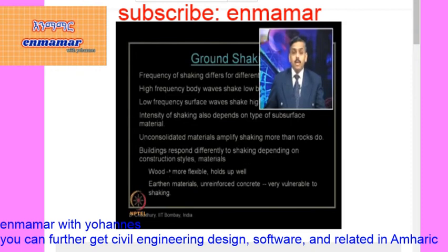That's why in earthquake-prone regions or hilly terrains, mostly wooden constructions are preferred, whereas earthen materials and unreinforced concrete are very vulnerable to shaking. As I have already mentioned, mud houses or masonry structures, or wherever reinforcement is not provided in the concrete, are very vulnerable during this ground shaking.